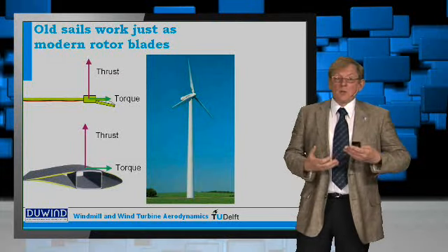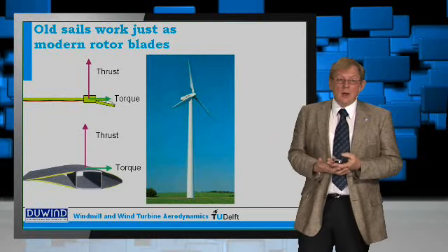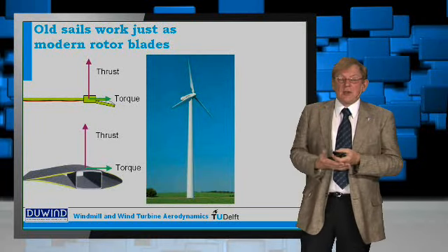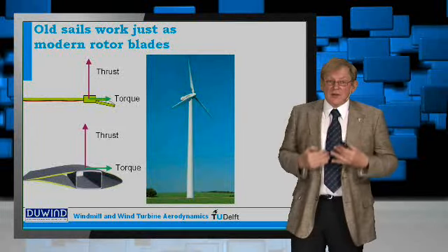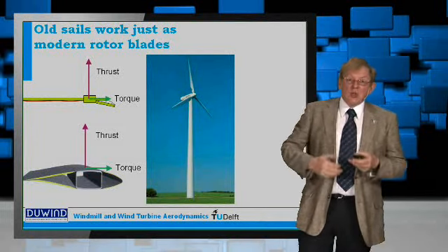Apart from thinking in terms of lift and drag, you can also think in terms of thrust and torque. Thrust is actually the force that the wind applies upon the rotor in the direction of the wind, and the torque, that's the component of the force that you use to extract the energy.